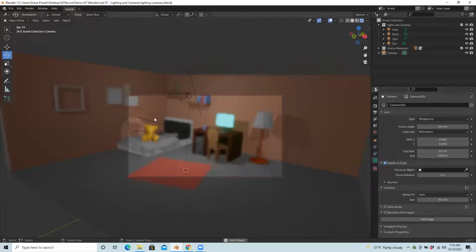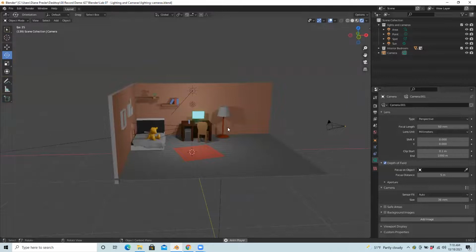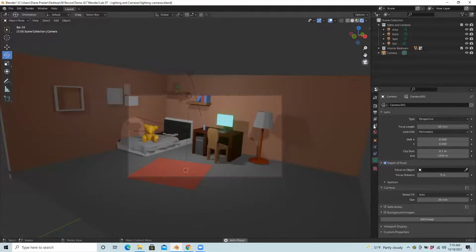And you can see that's actually causing almost my entire scene to blur because my camera is much farther than a meter from these objects. I just thought it's nice to see a dramatic change. So you could experiment with that. At 5 meters, I still actually have a lot of blur on the main objects. So it's still kind of looking at how far away from your objects is your camera. What's the distance there? So maybe the 10 meter was accurate. I can go back and reset that and preview it while I'm in the camera view.